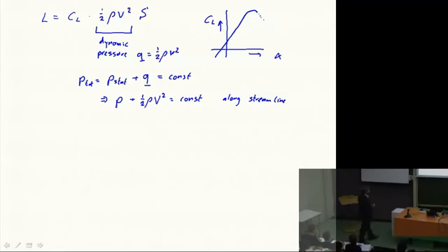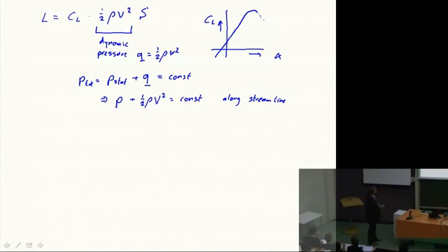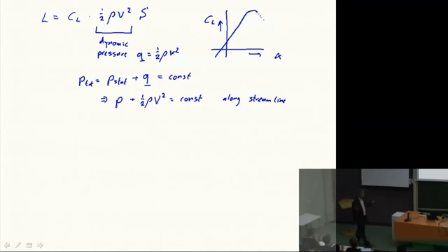It increases quadratically with the speed, and is also a factor which scales all the aerodynamic forces and moments on an aircraft. So if v squared becomes twice as high, all the forces will be twice as high. And rho, of course, directly represents the amount of mass that you feel, so there it scales linearly. So this is very important to keep in mind, the dynamic pressure.